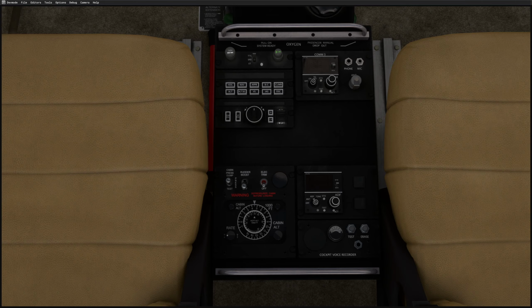We finished the last video looking at passenger comfort, looking at the temperature and things like that. This continues that theme really. We're looking at the cabin pressurization. It takes warmed and pressurized air, bleeding it off the engine, and we can control the altitude that the cabin appears to be at. So we're trying to keep it at a comfortable level, so oxygen levels and that are fine.